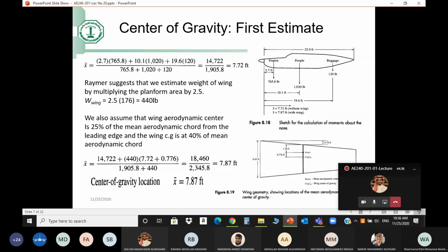But the location of the CG is important for stability. So what designers do is calculate all these values of CG. So it's not like a single value. We have so many of them, 10, 20, depending on the different possible configurations, with or without fuel, with or without passengers, with or without luggage, pilot only, and so on.